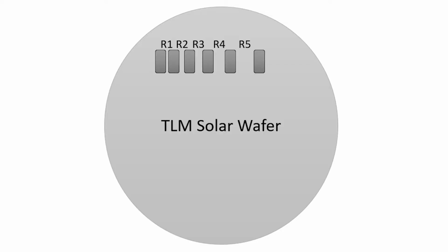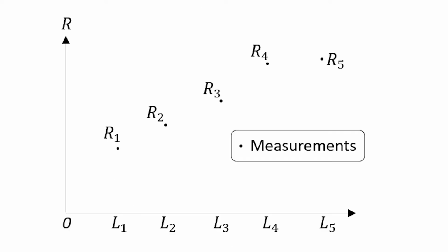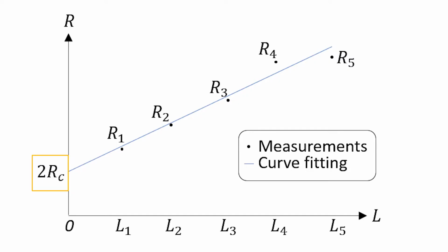Contact resistivity is one of the most essential metrics to measure how easily electrons and holes can pass through the interface of semiconductor materials. Traditionally, to get the resistivity, we need to measure the resistance across each two adjacent contact pads on the wafer, then apply line fitting to find the contact resistance. After that, we can derive the resistivity from it.